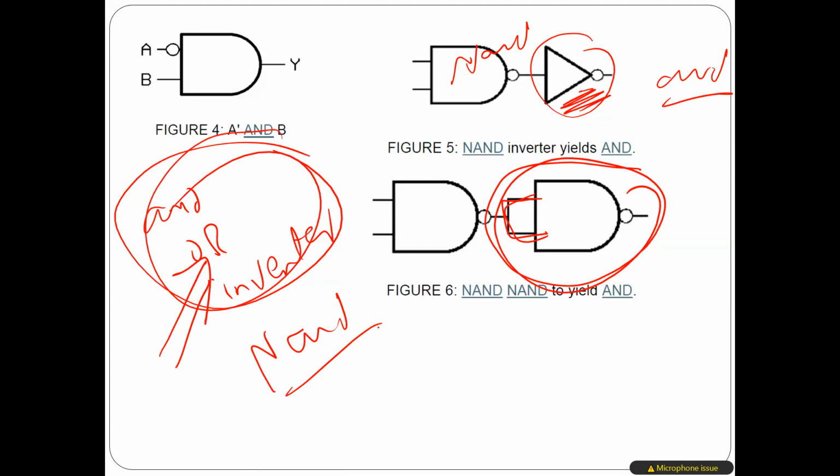Same thing for NOR, by the way. That's why if you have a nice electronic circuit for NAND, I can use this circuit to implement everything. So everything will be NAND, okay? Because simply with this NAND, I can easily make AND, it can do OR, it can do inverter as well. In the case of an inverter, as I told you here, you just tie the inputs. In the case of AND, you just put two NANDs this way. So this one is like an inverter.